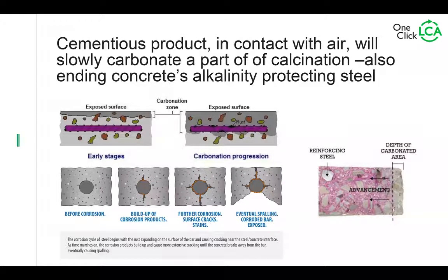And when you have elements cracking, you have a major service life problem for the building or for the element in question. So the carbonation is a two-edged sword, you could say. It provides desirable climate impact reduction, but you have to be very mindful of not exposing the steel to rusting.